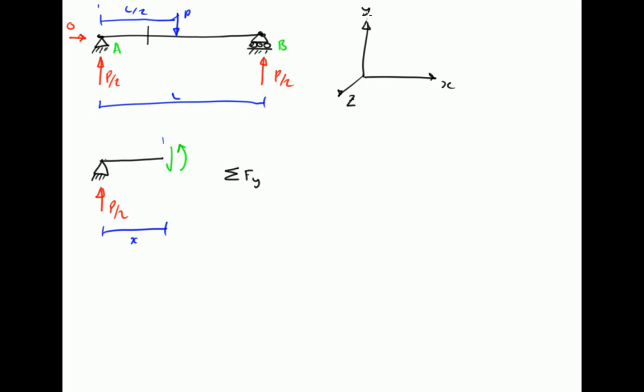So the sum of the forces in the y direction, so the sum of the vertical forces, the shear force, which we will call V, and the internal bending moment we will call M at x, and V at x. So for our forces in the system, all the forces in the vertical direction going positively upwards minus those coming downwards, the shear force, have got to equal 0. Again, that's from our principles of static equilibrium. For this to be in static equilibrium, this force at the reaction has to be balanced by an internal shear force, which is equal and opposite.